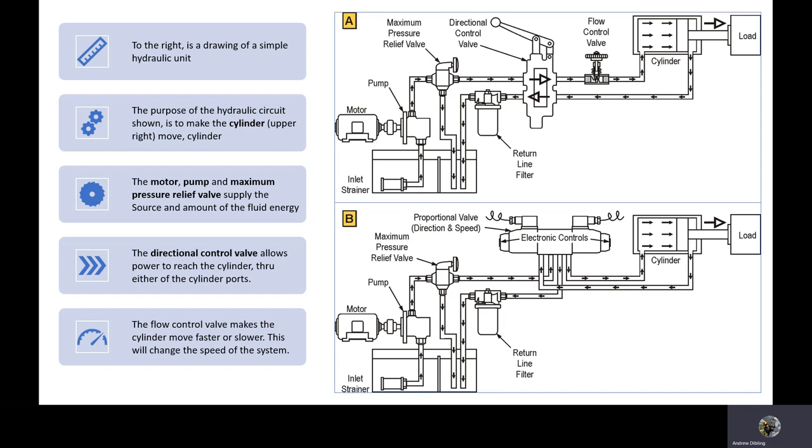If they don't, that can lead to damage to the system or decreased performance. So it's very important that the fluid is allowed to cool and settle. The reservoir does this by providing the fluid a place to come into and settle down, drop any contaminants that it may have picked up while going through the system. And here you see a baffle which prevents the inlet strainer from sucking in air or dirt.